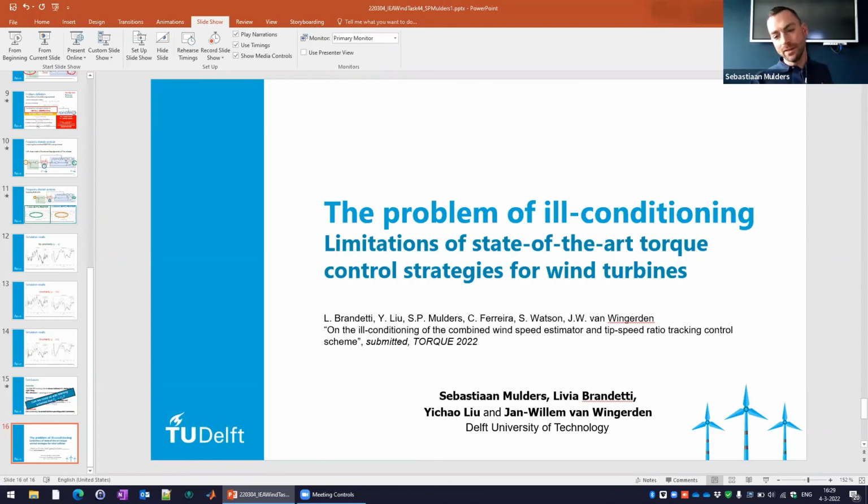But if the estimation of the individual turbines is already inaccurate or biased, then the whole wind speed estimation in the wind farm might also be incorrect. So I think indeed that we have to start correcting or updating these curves in individual wind turbines, and that wind farm control strategies can also benefit.